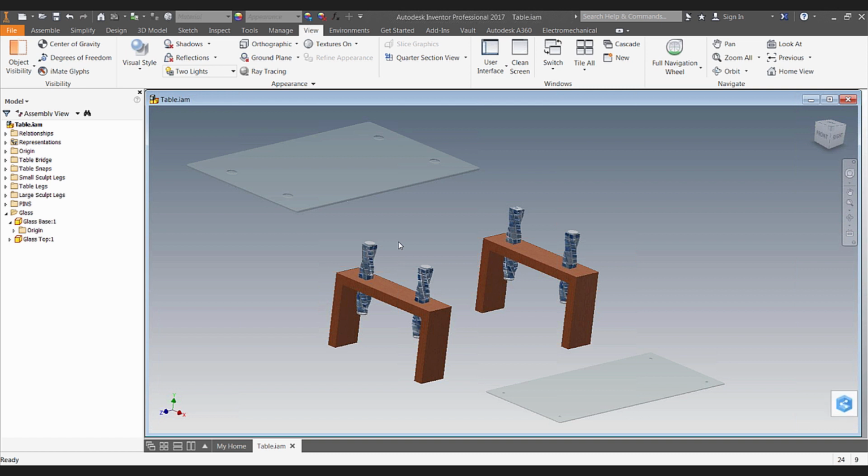They went into bolted connections to make that easier, but the content library itself has iMates already built into it. And so you can generate your own parts in that manner. But let's look at just how to actually author an iMate and use it in its most simplistic form, without defining the other half of the constraint set.